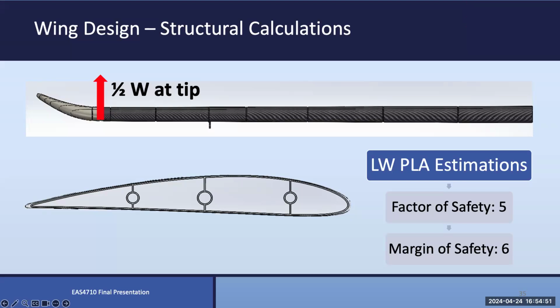Yeah, good. I mean, that's what you should do. That might have come from me. So, yeah, again, assuming this was your design load case, then you're telling me that you can hold 5 times that, but the margin of safety tells me that you can increase your load by a factor of 600% and still show good at your required factor of safety, right? So essentially what you're telling me is you can carry 30 times your limit load here, which is substantial.